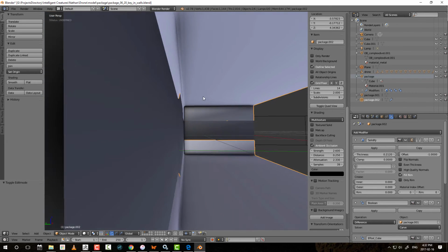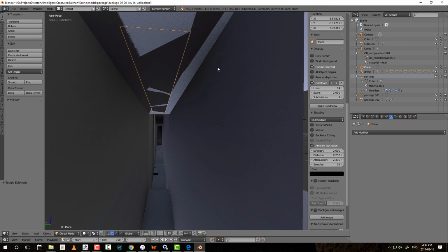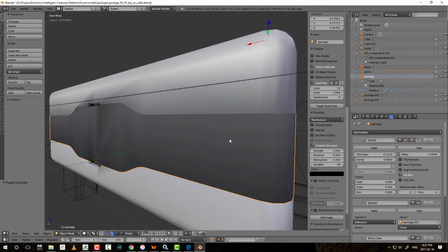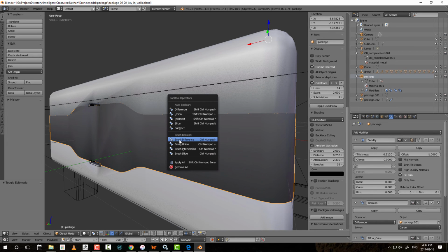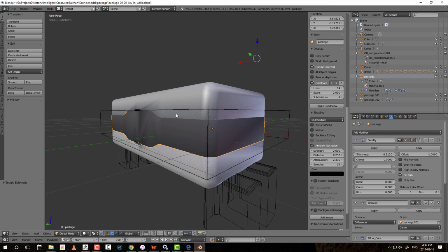And now first of all, you're going to get a bounding box, so at least you know exactly what you're selecting. So select the bounding box, zoom out, select the middle portion, Control Shift B, union. And it's going to be hard to tell what's changed. The reason being is that these brushes here, they're always in the same place. So if I try to move the actual object or geometry in any way, it's never really going to show you what the exact result is until you've finally baked the result.